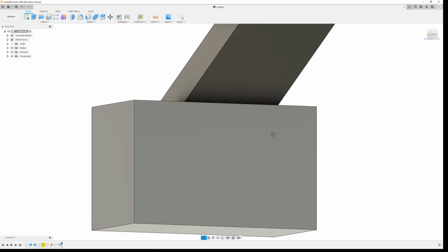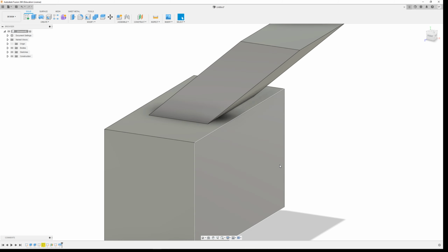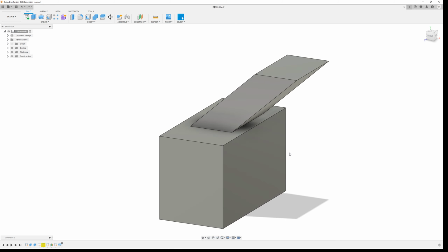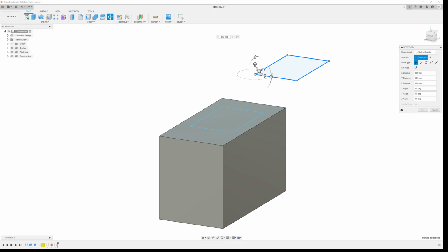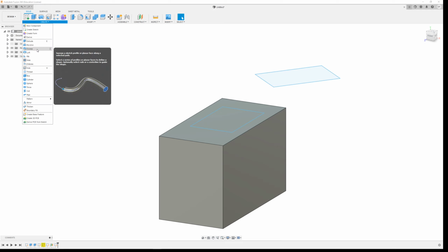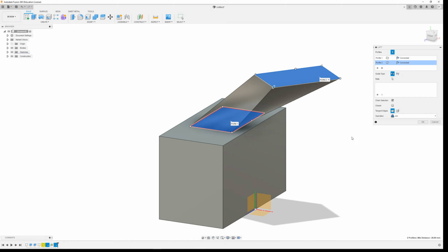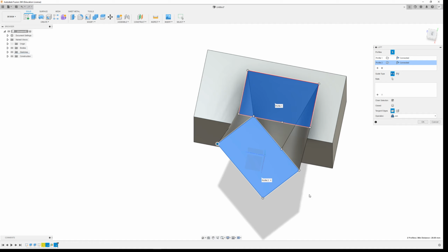We have the parallelogram. Now, Loft is a much more powerful tool than just doing a parallelogram, because it can do different shapes. For example, if this shape was slightly different, we can edit this sketch over here. Can we rotate this sketch? In theory, if that sketch was rotated, we can still use our lofting tool. But if we just want to make a parallelogram, we can, and it's going to be a lot simpler.